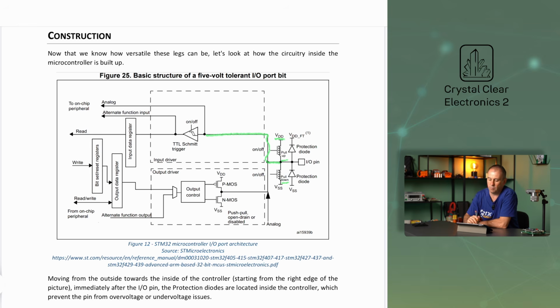The other mode is the pull-down mode. In this case, the lower resistor is connected between the ground and the leg. The upper resistor is not connected. The leg shows a low logic value in the default state, and an external device can pull it up to a high logic value.